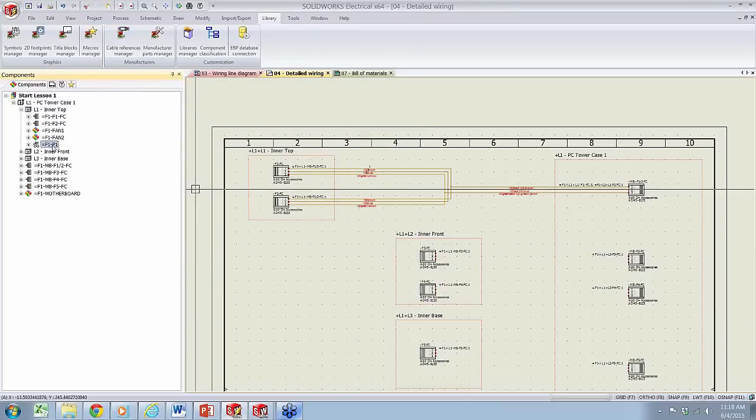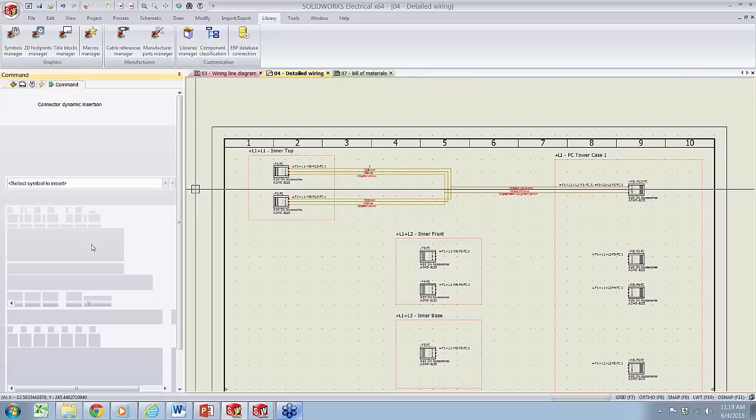So now my part shows in my tree. So that's what I was talking about. I can add all the components without inserting them first to my schematic, or the mechanical engineer again can add them to the tree. And because we share that same navigator tree, all the information that he adds into his tree will pop up. So all the mechanical parts that he's inserting to the assembly, it will show up on my tree as well. And at that point, I can go ahead and insert that connector.